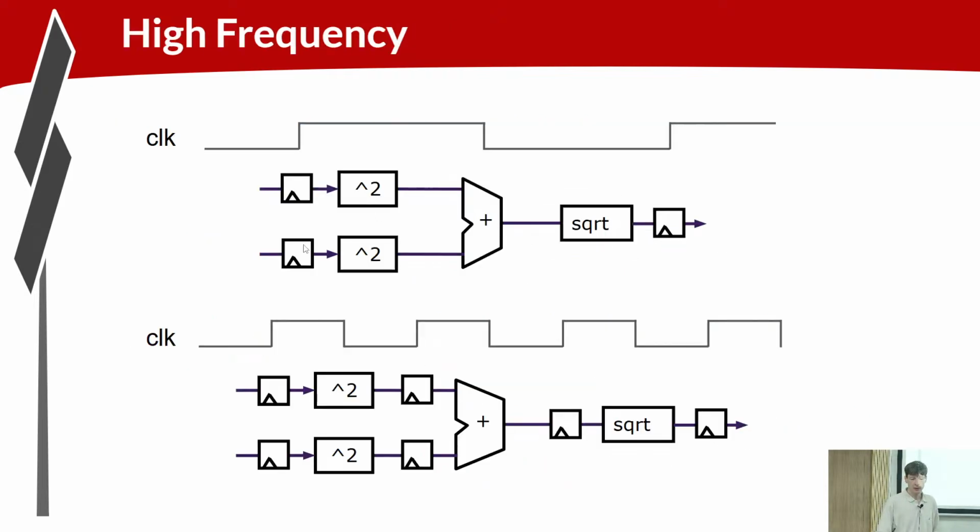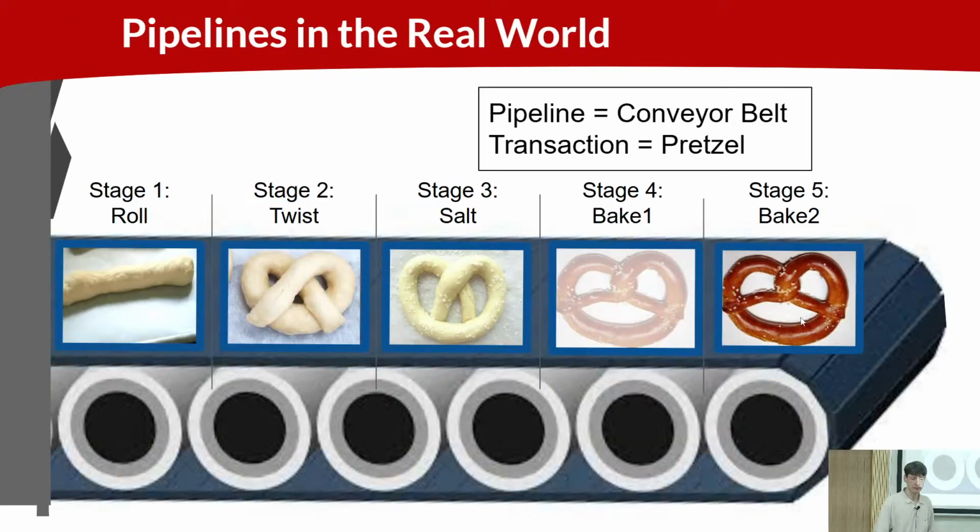So before, without any flip-flops, we're assuming that we can do the entire computation in a single clock period. If the clock is running faster, we can't. So each of these steps is accomplished in one clock, and it takes three clock periods to do the whole computation. Okay.